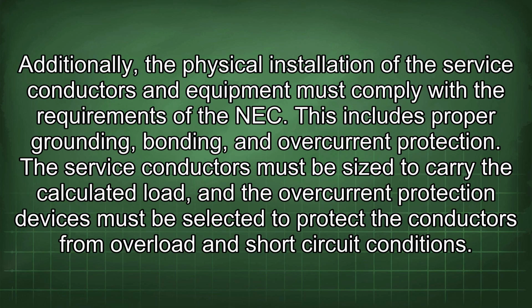Additionally, the physical installation of the service conductors and equipment must comply with the requirements of the NEC. This includes proper grounding, bonding, and overcurrent protection. The service conductors must be sized to carry the calculated load, and the overcurrent protection devices must be selected to protect the conductors from overload and short-circuit conditions.